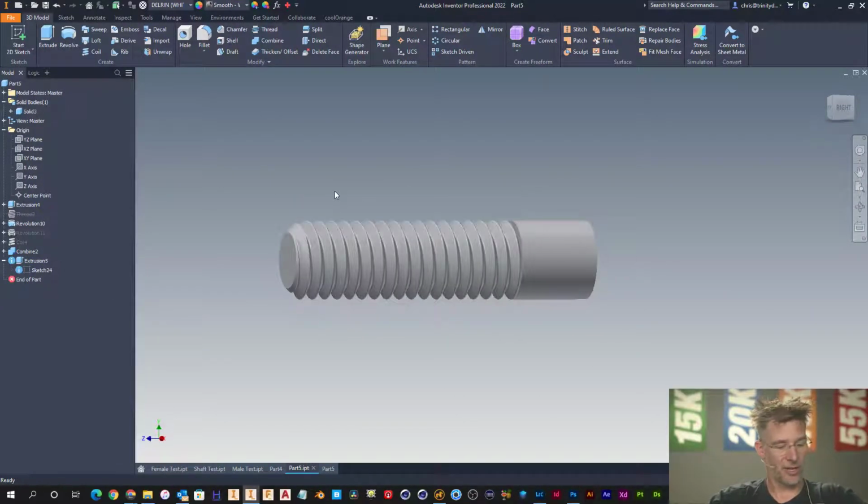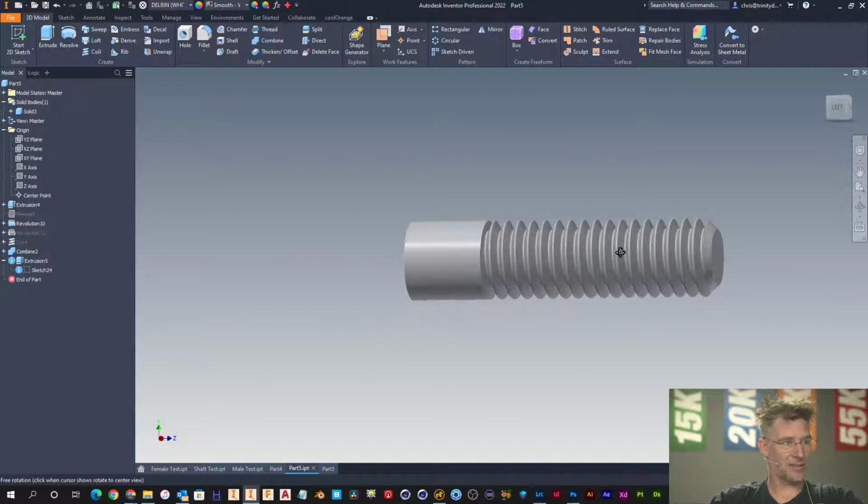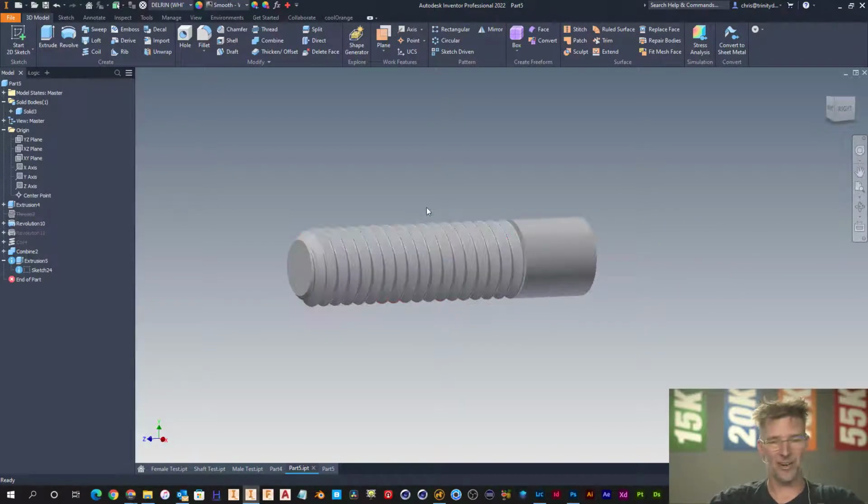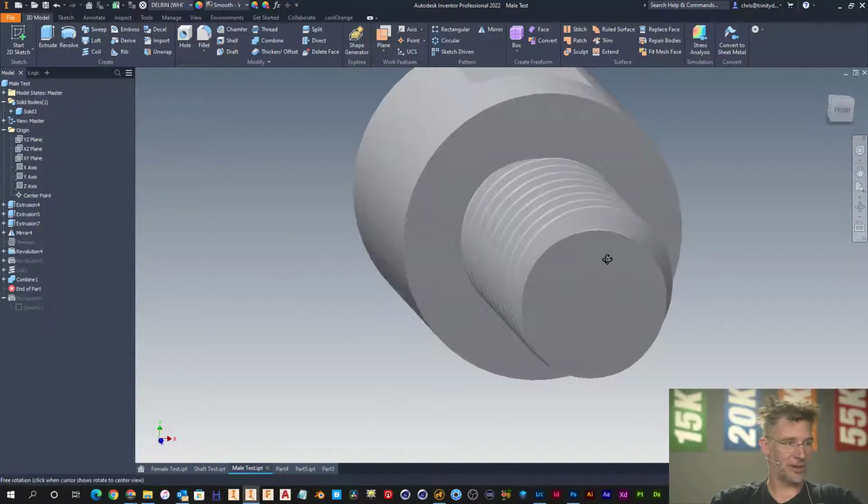Okay, so there we go. That's what we've got. We cut our thread, we changed it. That's how you do it with Cool Orange. It's not very user-friendly. You can't go back and just change it. It's one of the things I like about SolidWorks, because when you cut physical threads, the thread tool stays active and you can change it on the fly to whatever you want. So now what we got to do is figure out how to manually cut these threads on our end.